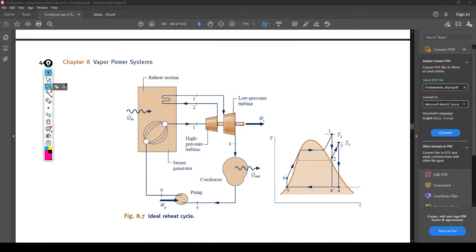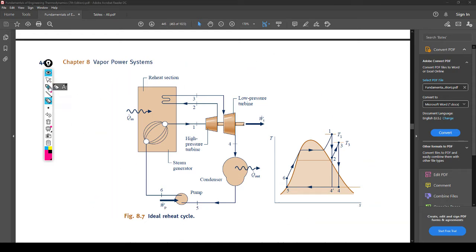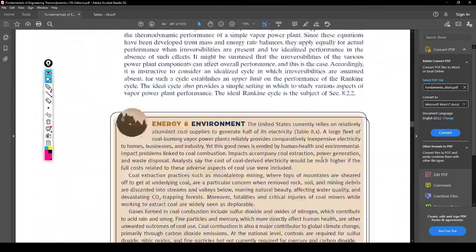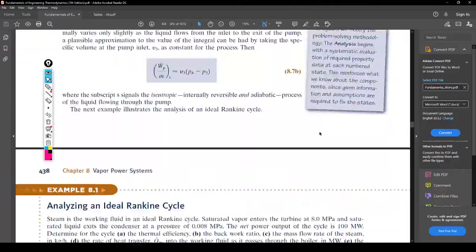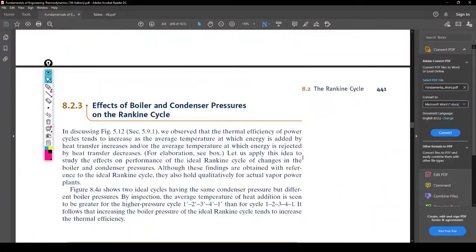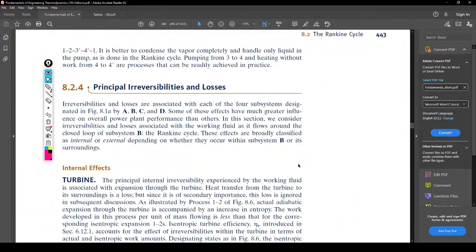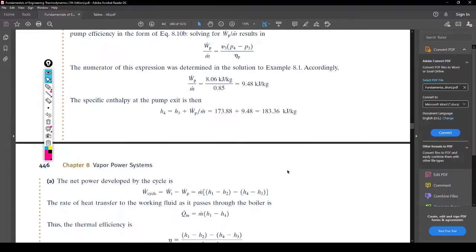And this right here is very common. This is something that will be in a lot of cycles. And all cycles, and I mean all of them, are superheat cycles. I can't imagine there would be a cycle that is not a superheat cycle, where they just do saturated vapor. I would be completely shocked if there was. So basically all of them look like the one that we did afterward, not the one that we did earlier.